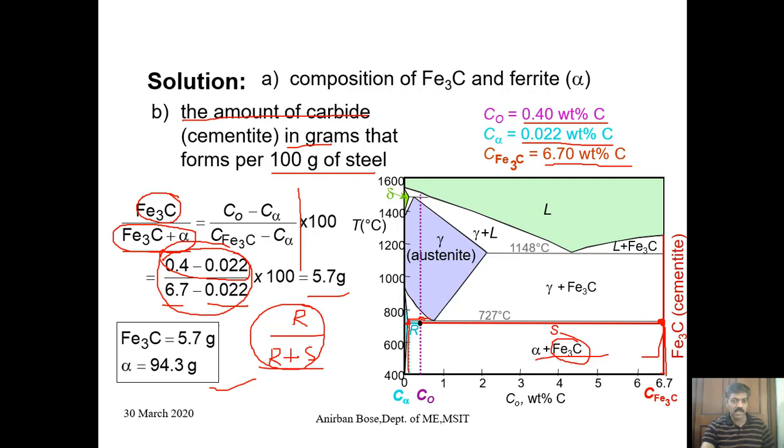Now this austenite part, when you are further cooling, this austenite part is actually forming the pearlite, right? And this ferrite part that already has been produced is called the pro-eutectoid ferrite. So basically you have to find out the amount of austenite just above the eutectoid, that's all, because that part actually converted into pearlite.